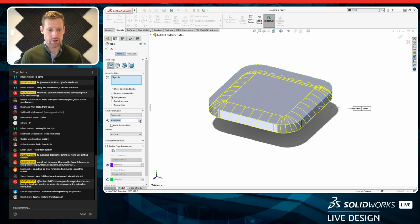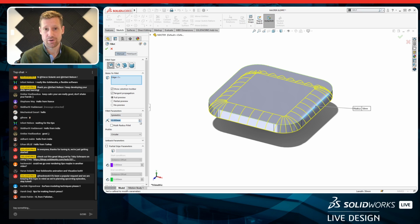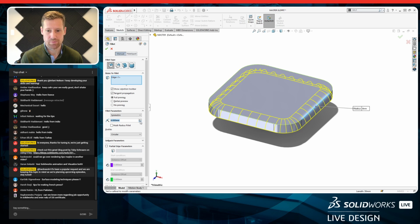And here's something else that I think is a little bit odd about how SolidWorks does things. If I hit the up button here and I say, oh, I want to increase that fillet by a little bit, it's going to increase it by 10 millimeters. It seems like kind of a lot. So a tip that I learned here in live design is if I hold the Alt key and I click on one of these, it'll just reduce it or increase it by 1 millimeter. So that's a really useful tip. So I can keep reducing it or increasing it. And as we can see, 5 millimeters seems about right.